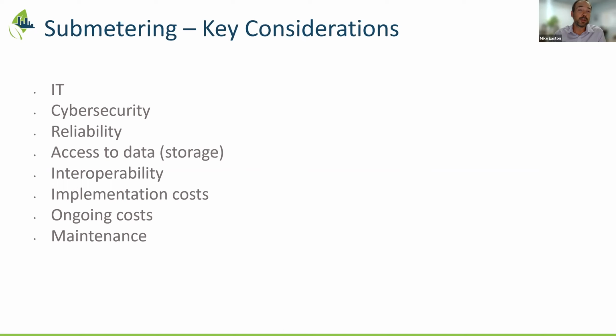If you are going to be doing a web-based solution or getting the data out of the building, I believe the historic way that properties have wanted to do it is utilizing the base building network. But we've really been finding this a struggle lately, whether it's an institutional portfolio or a commercial portfolio. Integrating with the base building network to hang metering on it is actually quite a challenge. So what we've really been moving our customers to is a cellular solution, where the meters are completely independent of the base building network, but they have a direct cellular communication.